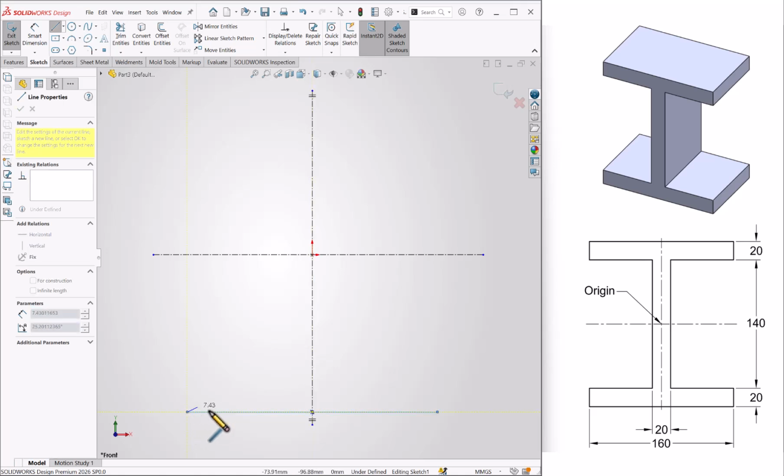You will notice that as you specify the endpoint of the line, a mirror image is automatically created on the other side of the mirror line. The line drawn as the mirror entity gets merged with the line drawn on the left. Therefore, the entire line becomes a single entity. But the line will merge only if the endpoint of the line drawn is coincident with the mirror line.